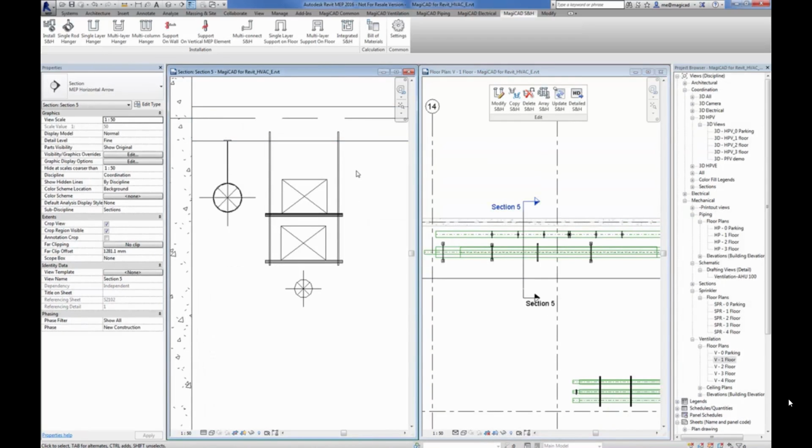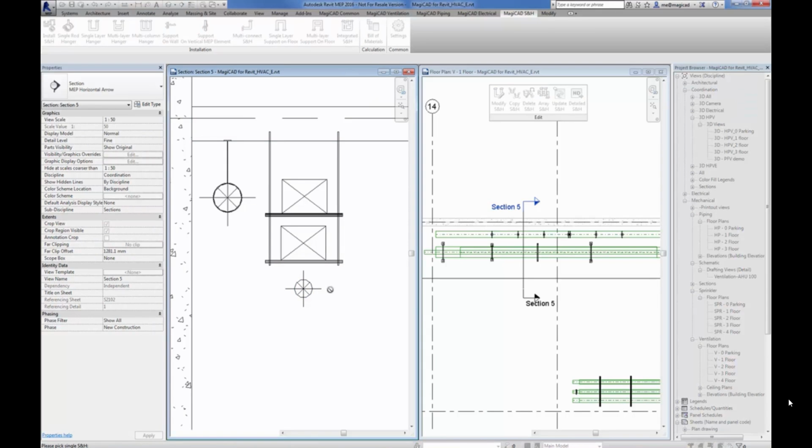One of the powerful functions in the supporting hanger tool is the integrated supporting hanger, and in this case I'm going to make a coordinated hanger type. So I'm going to combine hanging this new duct with an existing hanger type. I go to the integrated hanger, supporting hanger type, select the specific hanger, and then the duct I would like to hang, and then click finish.